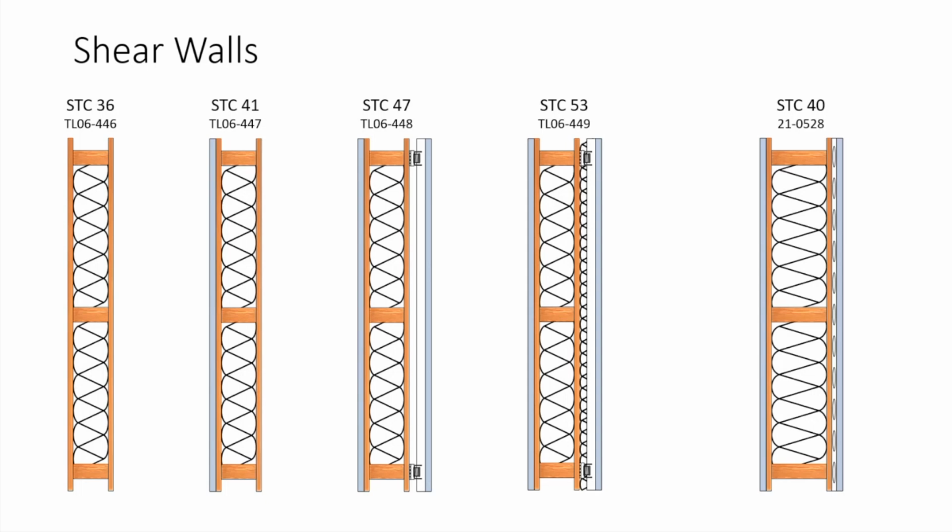And so you can see there on the far right, this is a different test series. This is a 2x6 wood stud wall, but this just had resilient channel and drywall over the shear layer with no insulation in the air cavity. And you can see that's not a well-performing wall. So just adding resilient channel is not effective enough to isolate that structural transmission path.